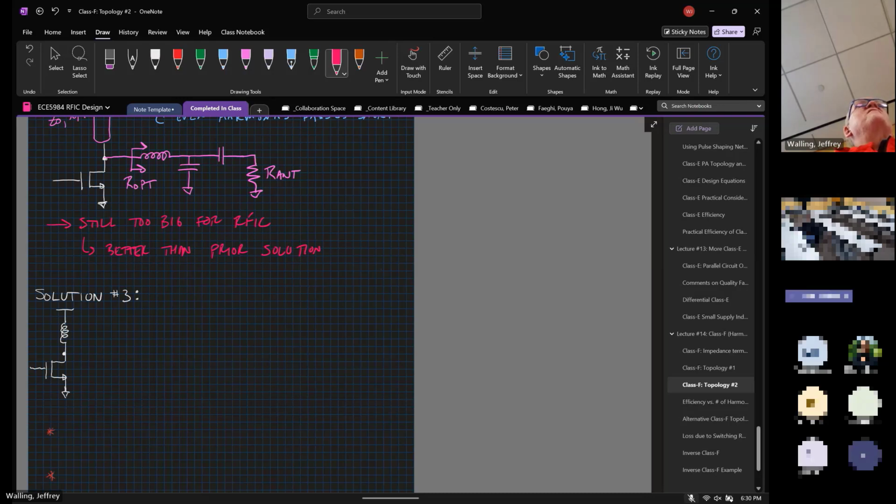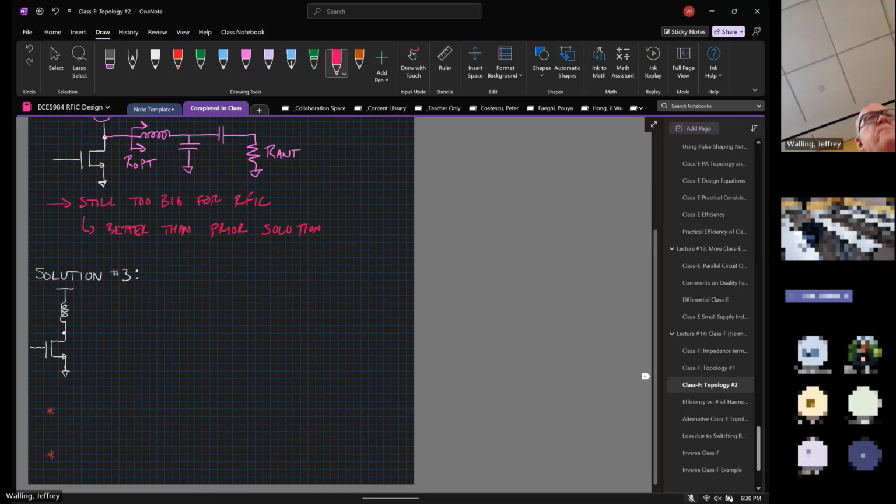So you're already going to be having them add some decoupling capacitors and things like that. Now you're going to tell them, you also need to add a few extra additional components plus a transmission line. Probably not going to work. You might not sell a lot of parts. But is there some technical restriction? Because like the wire bond directly to the drain, it seems like it would be really overpowered, for research at least, to just have some really high Q inductors and capacitors off chip all the time.